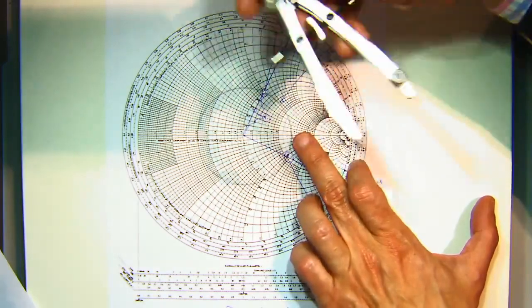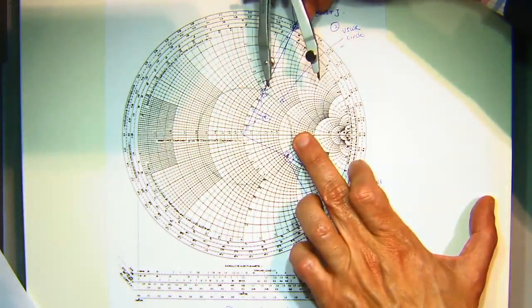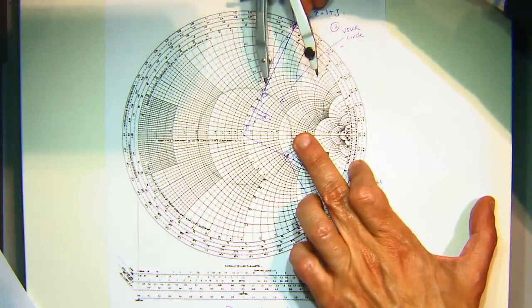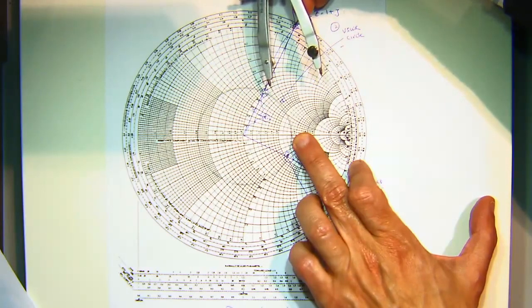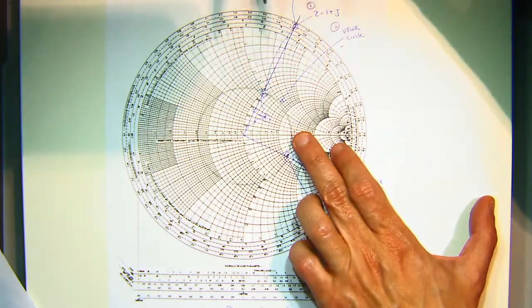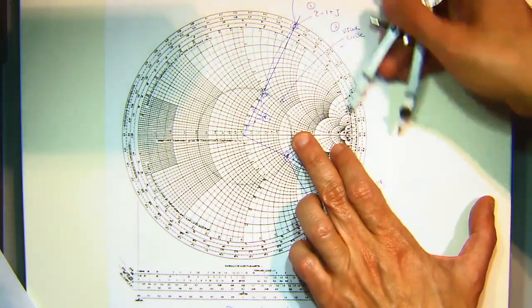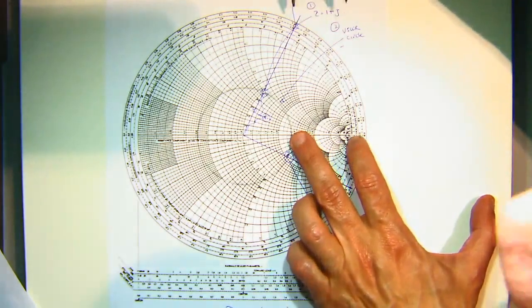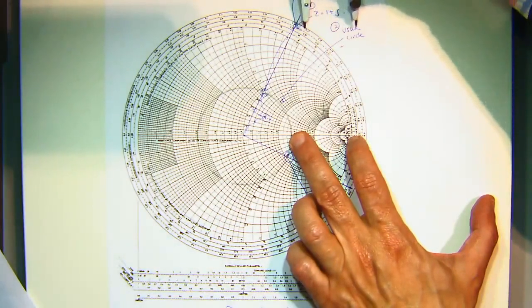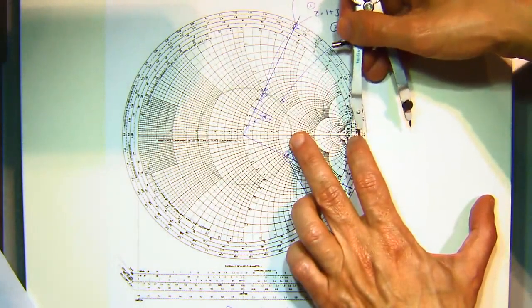And not to go through example number 2 again, but if I asked you specifically, like in example 2, what length of line gives you the maximum impedance? Can anyone tell me? All right, so we're going from here to here, right? So what was the value here? It's 0.16 lambda. So 0.16 lambda is going to give you your maximum impedance.